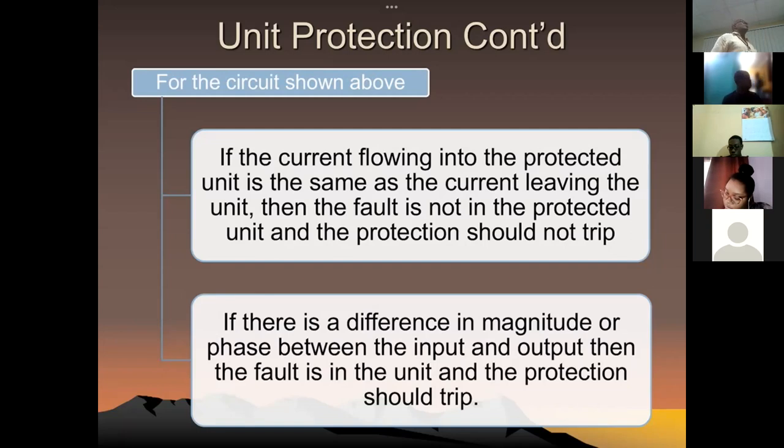All right? So the reason I mentioned that is because when you de-energize a transformer, if the level of magnetism should fall significantly, then in re-energizing the transformer, what you will have is a significant current at the input.